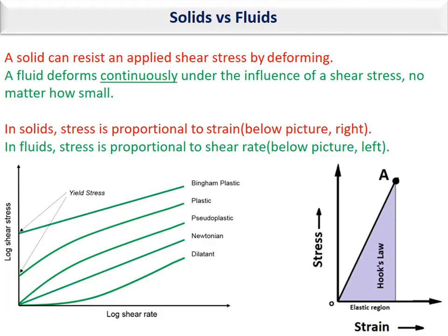The first thing to discuss, and I want you to learn it, is the difference between solids and fluids. As you can see here, a solid can resist an applied shear stress by deforming. It means that when you apply stress on a solid body, it will be deformed. A fluid also deforms, but there's a difference which I underlined here, and that's the word continuously.